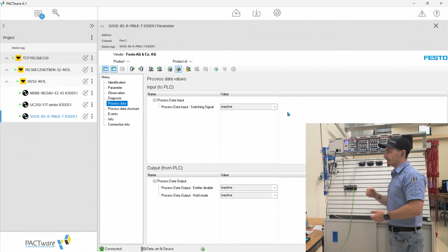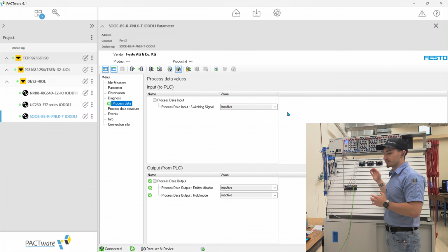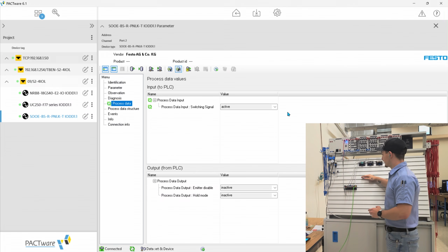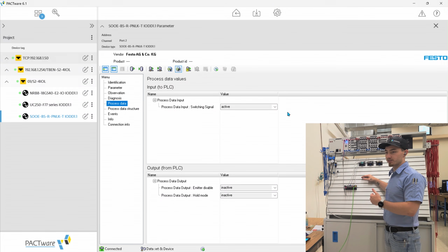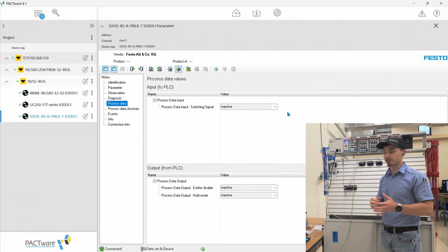So it shoots the light back and then it receives it, and that is interpreted as a 0 if it does detect the light. But as soon as a product or something goes in front of it, that breaks that connection, and that's interpreted as a 1. But if it detects the light, then it's a 0. Okay, so I had that backwards.